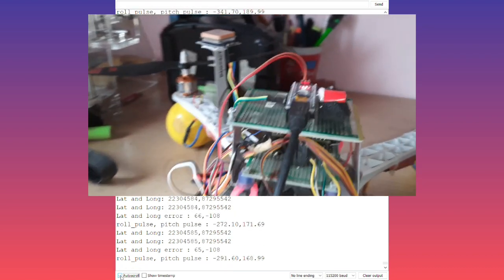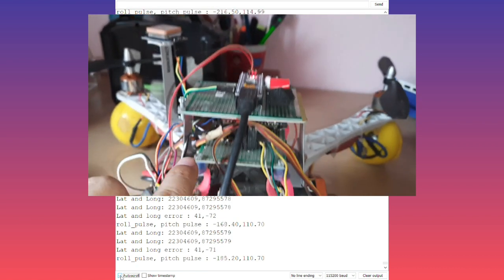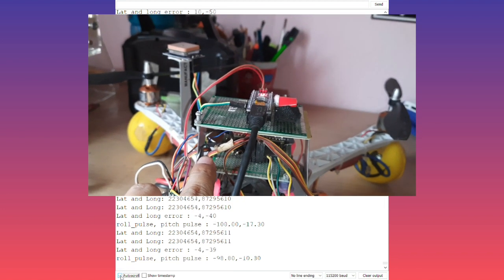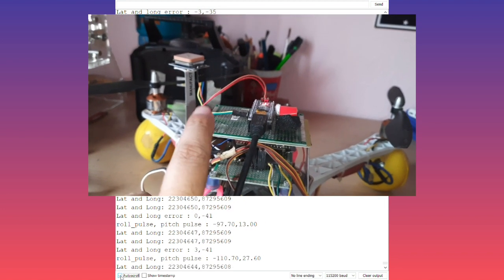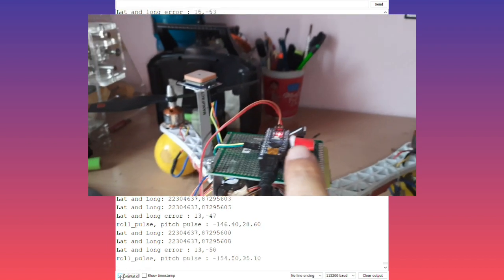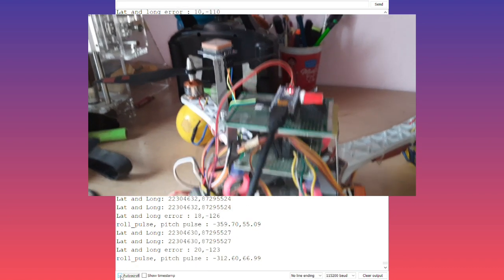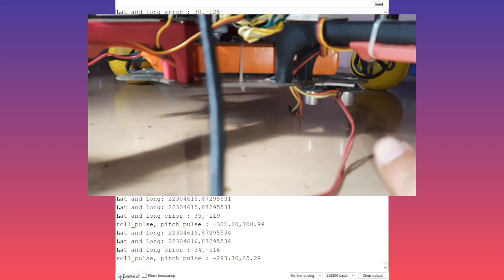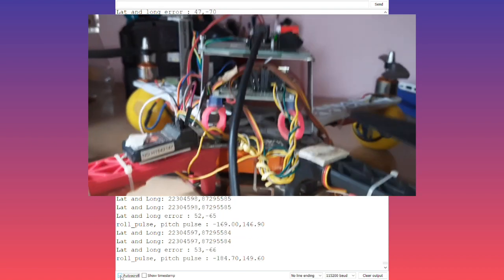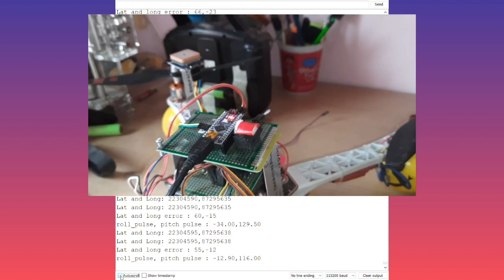Like I have explained, this is the flight controller, which has the inertial measurement unit and operates at 200 Hertz, and this is the secondary Arduino Nano which is acquiring data from the barometer BMP280 and the GPS module. I also have this ultrasonic sensor underneath, if you can see that. So all these three sensors are being governed by this microcontroller.